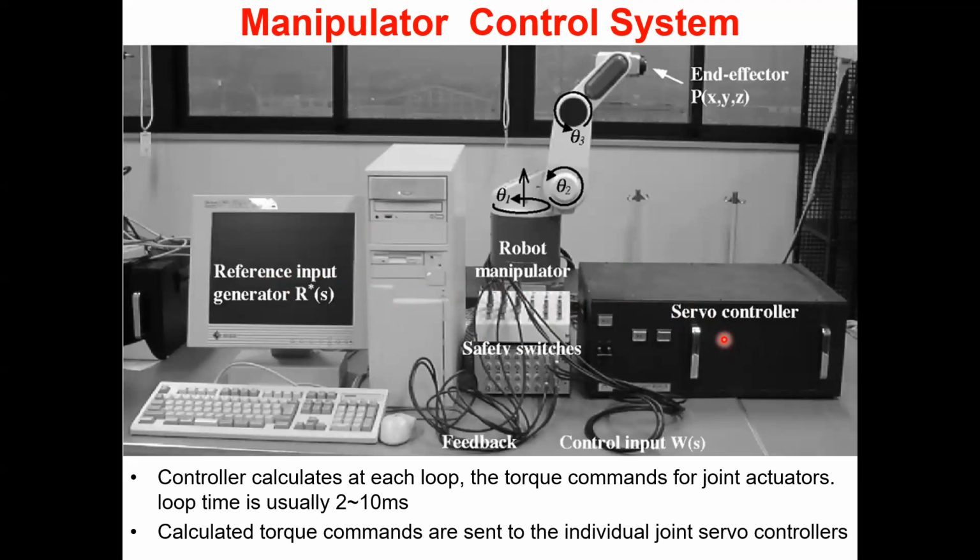So after that, what happens is that the servo controller reads joint 1 angle, the present, existing angle, through the feedback. You can see the feedback, right, coming from the joint encoders, theta 1. The servo controller reads what is the angle for theta 1 now.